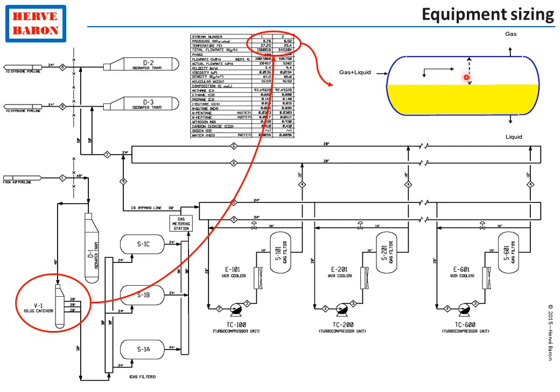Practically, the cross-section area for the gas flow is increased up to the point where the smallest droplets of liquid that are needed to be recovered in the liquid phase have their velocity reduced enough so that they will indeed fall in the liquid phase. This sizing is done for all the possible flow rates of gas and liquid of the various operating cases of the heat and mass balance.